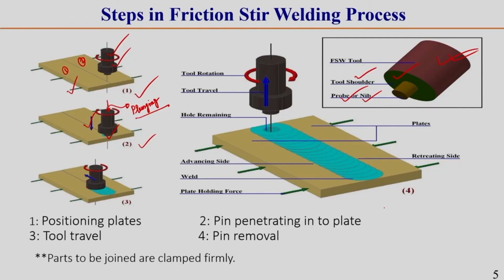So, that is why in the welding process you can observe different phases. This is one phase, that means from touching of the tool tip with the workpiece to touching of the tool shoulder surface with the workpiece, this is called the plunging phase. This I am writing here. At that time the material temperature is rising. What I am telling, understand.